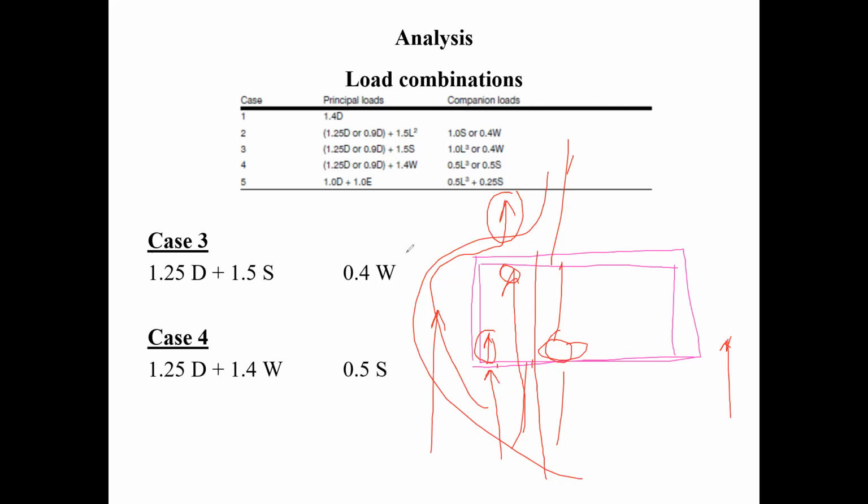For example, I don't know if you've ever seen refrigerated warehouses. It's mostly all refrigeration, okay? And therefore they have very little openings. I forgot what the values are, but they're very small for the internal pressures because there's very little openings. And then you got the ones where, for example, you have these loading docks. You know, these industrial buildings with big loading docks and big overhead doors. You understand? Yeah. Well, there they want you to use a gust factor of 2.0 because it's very likely that these things are going to be open during a storm.